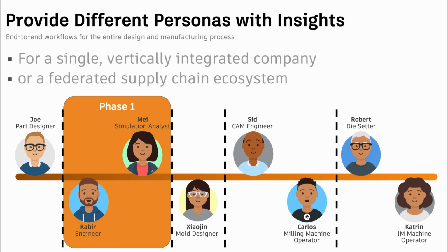The disconnects cause problems. How many times have you, as a Moldflow analyst, seen cases where the warp predictions didn't match, and then you start looking into it, and it turns out that the molder actually has a different process, or the analysis that you ran was on design version 4, where the part actually being produced may have been altered in significant ways that are no longer matching what you were running in the back. And there was just simply no time to connect, let's say, the Moldflow simulation again into the latest design changes.